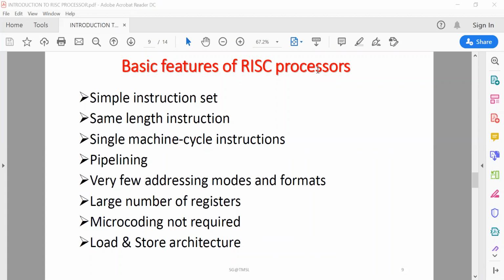Now RISC processors have unity clock per instruction execution speed, which is due to the optimization of each instruction on the CPU, and massive pipelining embedded in the RISC processor. Pipelining is embedded in a RISC processor, and that is the key to the speed of RISC machines.